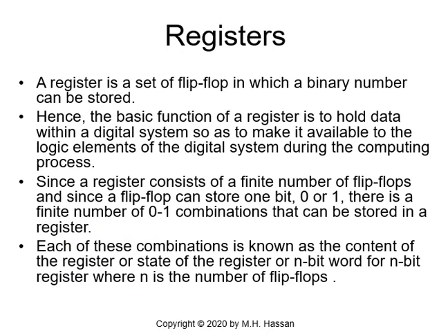What are registers? A register is a set of flip-flops in which a binary number can be stored. So a register is a memory element. We can store data in it. If we need to store 8 bits, or a byte, we need 8 flip-flops to store 8-bit data. And the data can remain there forever as long as the flip-flops are connected to a battery or a power supply unit.